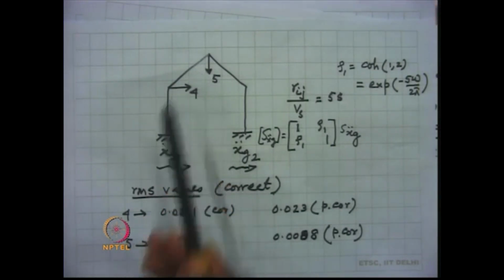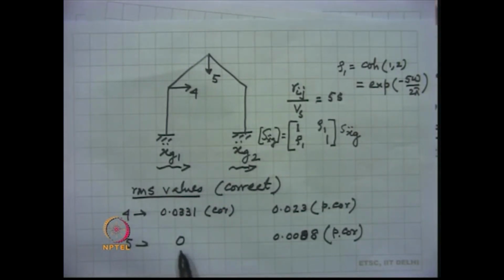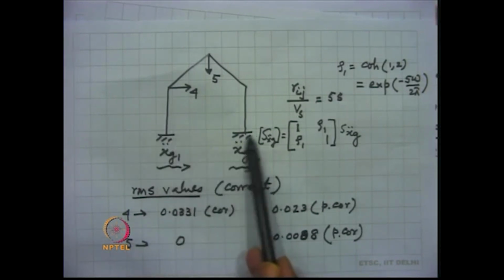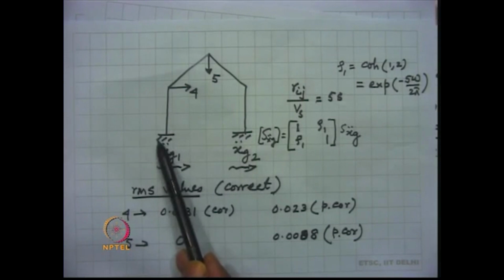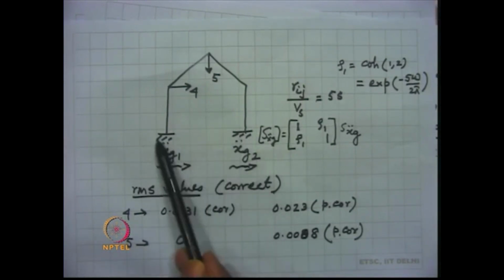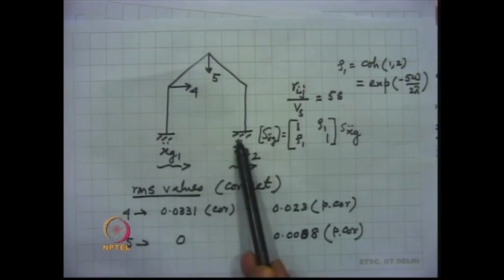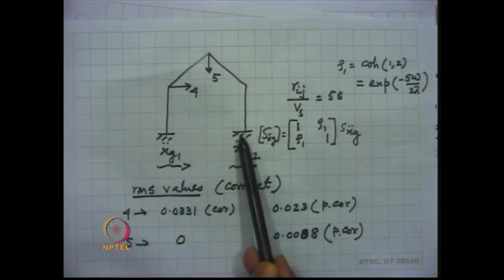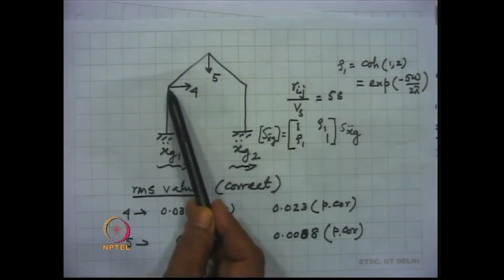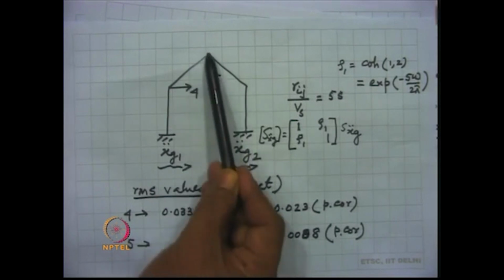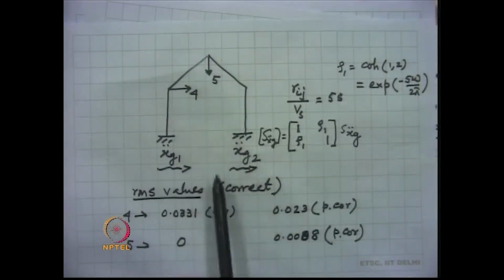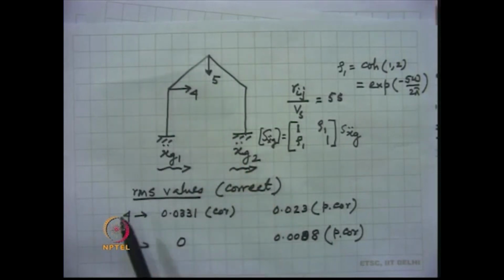For the displacement 5, when it was perfectly correlated, the value was 0, which is expected, because these two supports would be moving as a single unit, that is it becomes a single point excitation system, and in that case we expect that there will not be a vertical motion over here.